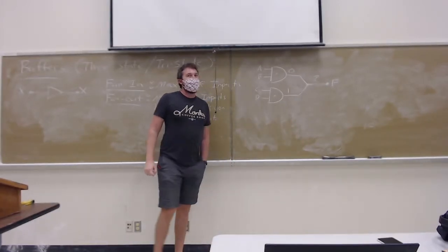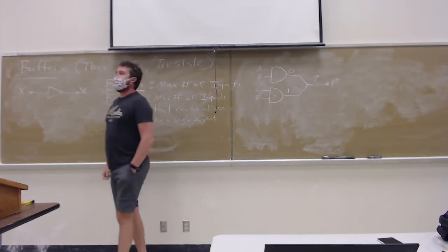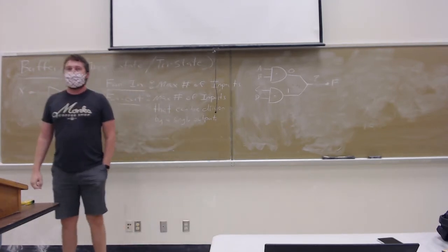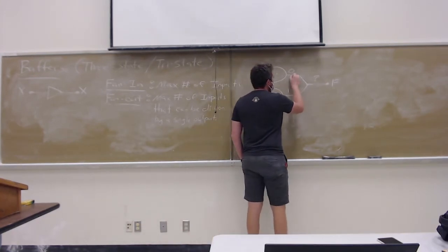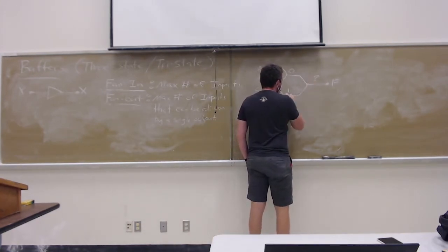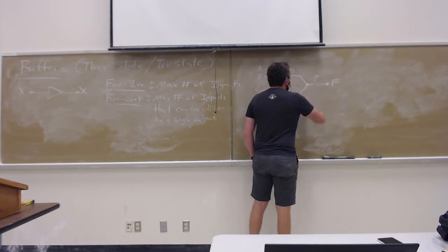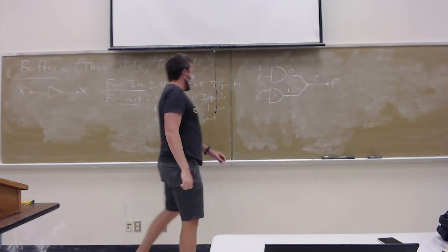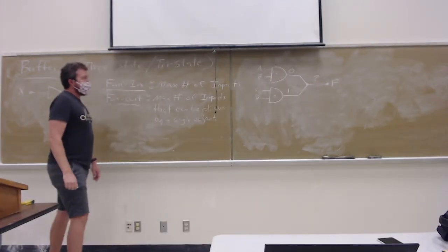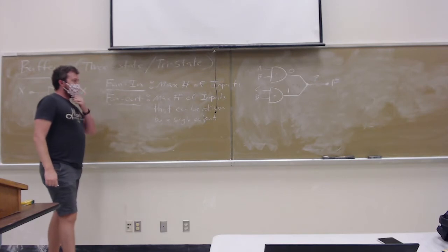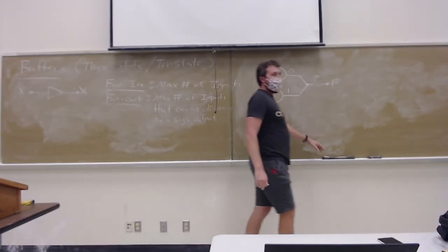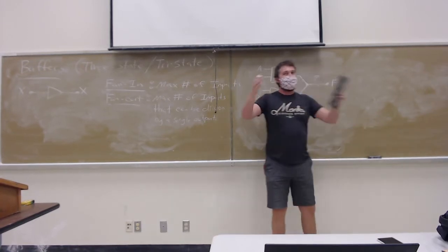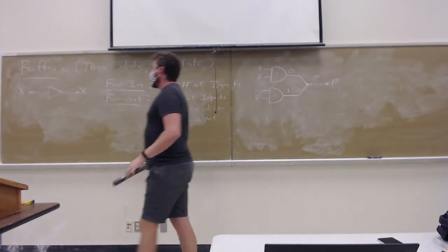You can't do it. The thing catches on fire. Plane crashes. The ship sinks, right? Bad stuff happens. Two outputs cannot come together to a single node. But there are a number of reasons why we would want to do that, right? Again, we saw multiplexers last time, which basically did this same concept. Let us condense down and select on a single line.